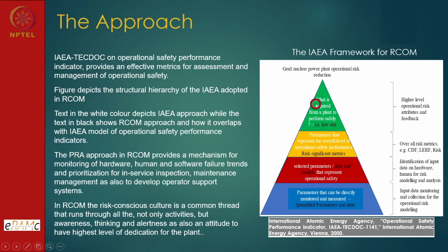So this is how to reach the goal of operational safety, through data collection and operation ecosystem performance, translating it into safety, with reliability data on human, hardware and software, and finally core damage frequency. LERF is large early release frequency, the output of level 2 PSA. CDF, core damage frequency, is the output of level 1 PSA.